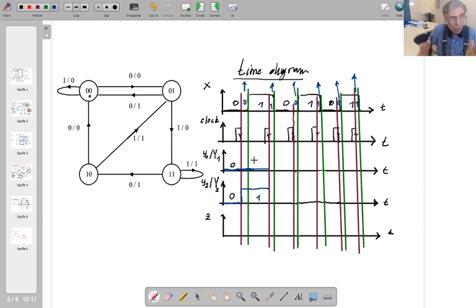In the other time intervals it's not going to change at all. It doesn't work. So that's why I draw that line until the next clock pulse negative edge. So that's 0, that is 0 as well, and that is 1, and that's 1 as well. So I have a change here. This change stays as it is until the next clock pulse comes.